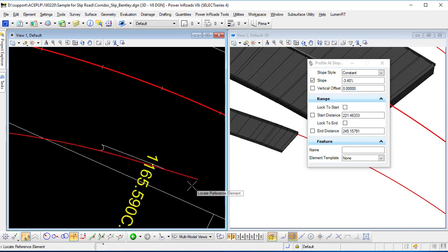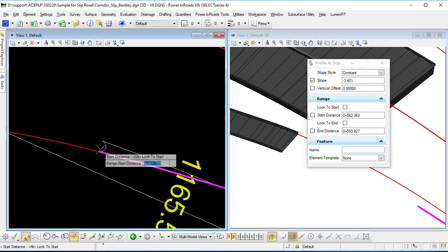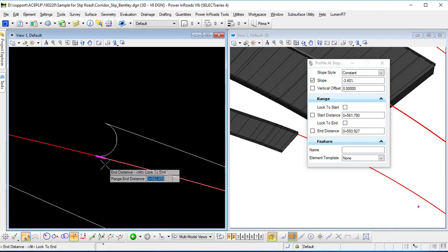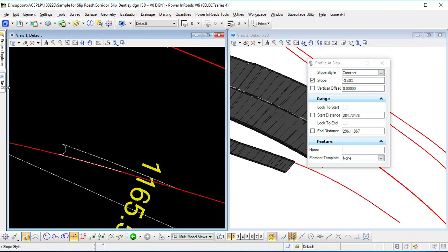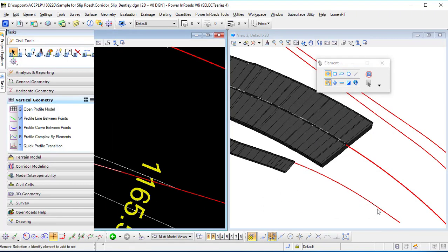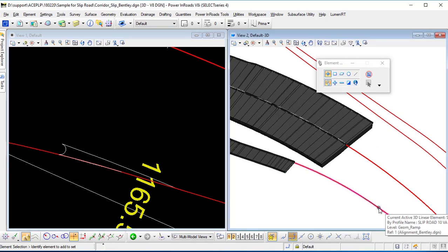Okay, and then select the reference elements. There's a reference element here, so you will select here. I want this one aligned here, and then to the end you can just snap here, or you can click a snap. There's a snap mode. Okay, to the intersection, with vertical offset zero. Then supposedly you have already created a new 3D alignment in the 3D view. So you can select a 3D view here as well.